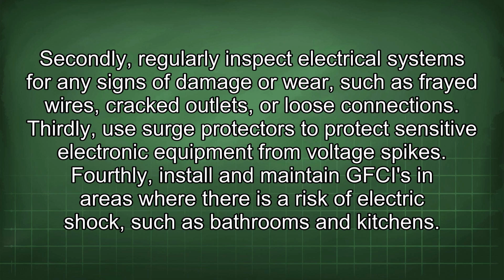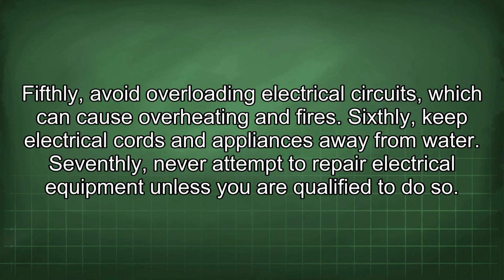Fourthly, install and maintain GFCIs in areas where there is a risk of electric shock, such as bathrooms and kitchens. Fifthly, avoid overloading electrical circuits, which can cause overheating and fires. Sixthly, keep electrical cords and appliances away from water. Seventhly, never attempt to repair electrical equipment unless you are qualified to do so.